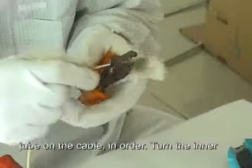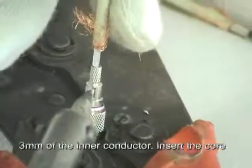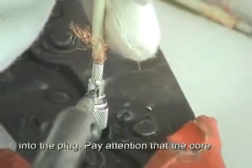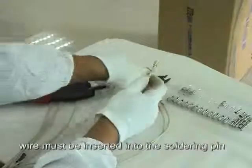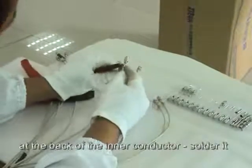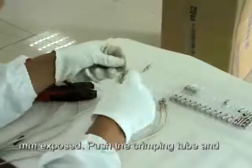Turn the inner part of the shielding mesh inside out and peel the internal insulation layer to expose 3 mm of the inner conductor. Insert the core into the plug. Pay attention that the core wire must be inserted into the soldering pin at the back of the inner conductor. Solder it securely and trim the shielding mesh with 6 mm exposed.